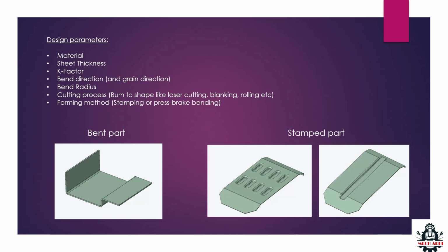Then stamped parts are basically tailored parts which are suitable for specific design requirements. It may be material stiffness or any formed features that serve a specific design purpose, or for airflow and to act as gussets, etc. So stamped parts actually require special tooling and cannot be made with conventional bending. So stamped parts are usually costlier to develop compared to bent parts, although the piece part cost might be comparable or even cheaper than a bent part in some cases.